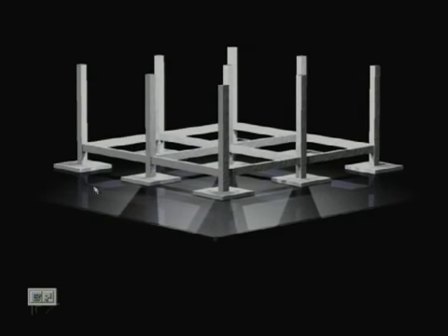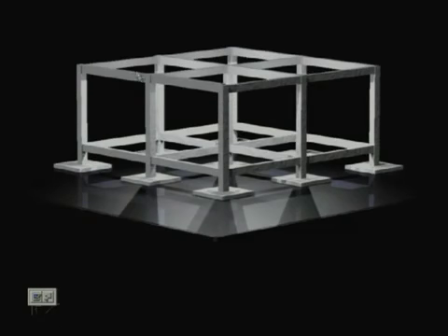We generally do not provide a wall footing for walls; we start from this tie beam, which will take the wall load. We can also take it for the frame, but we generally use it for walls.